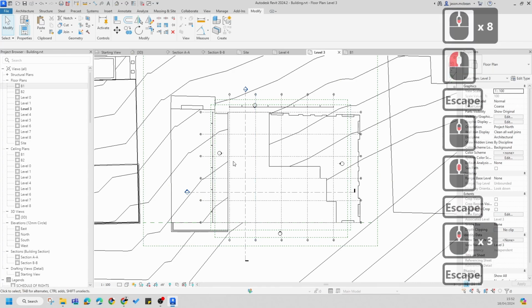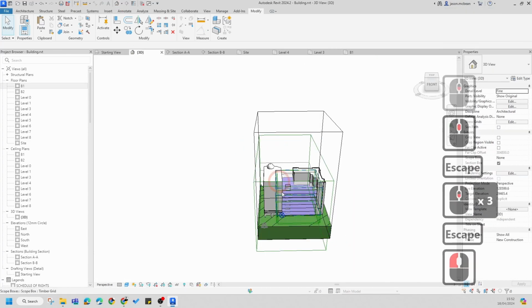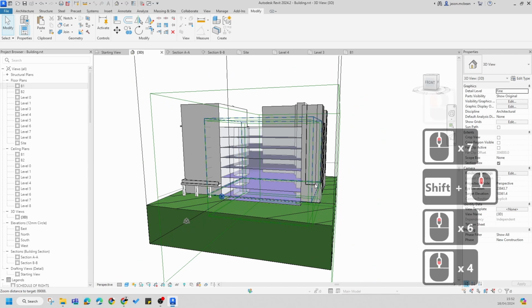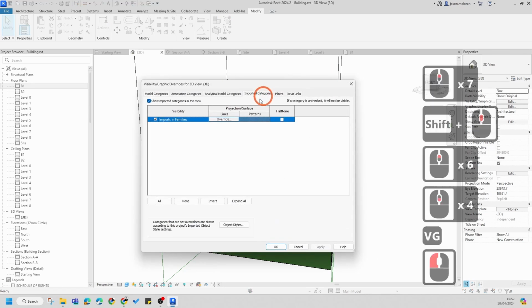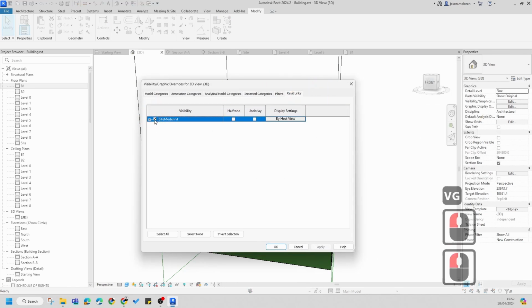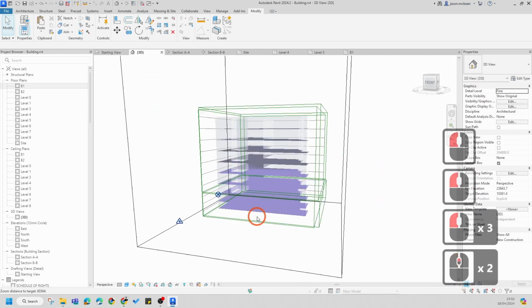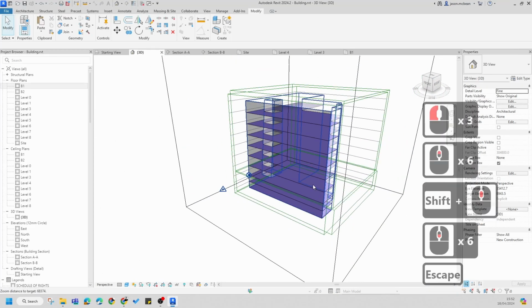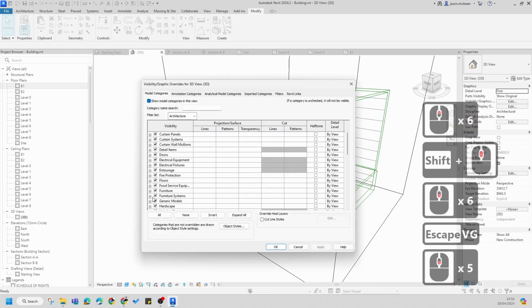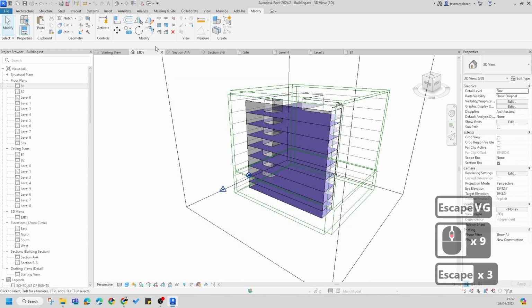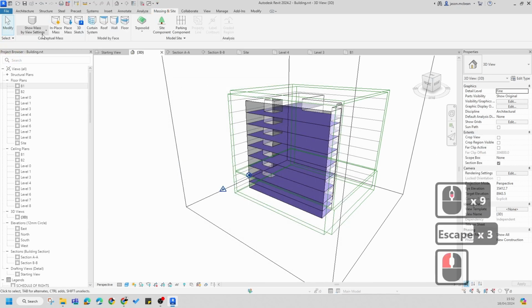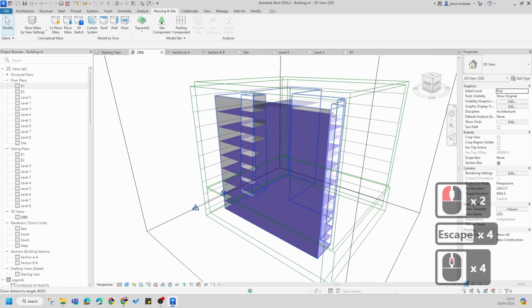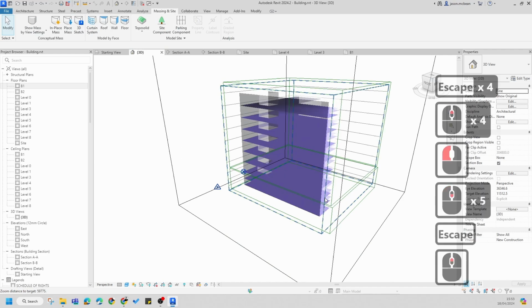Okay, now, once I've done that, the next step, and we're just going to create floors for this exercise. I'm going to go to VG, imported categories, and Revit links. I'm going to switch off my Revit file. Now, what's very important to understand by using masses: remember, if your mass is not visible, you need to go to VG and you need to switch it on. If you're using the massing tool by default, if you start using the tool, it will always say show masses. So technically, this shouldn't show, and there's a reason why we don't show it.